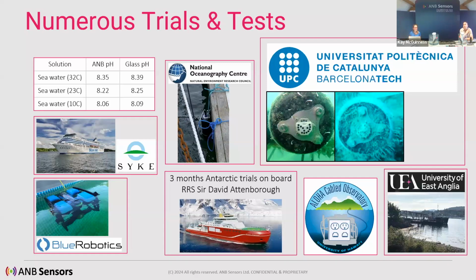We did some tests in Barcelona where we deployed two sensors. The one on the right-hand side has a lot of biofouling incrustations on its surface. That one wasn't switched on during the deployment; it was a control sensor. The one on the left had the monitoring switched on, and you can see there's no biofouling on its front surface. That's because we generate a small amount of peroxide during deployment, and that peroxide is enough to keep the transducer surface clean from biofouling. Obviously, peroxide breaks down quickly in water, and therefore isn't a long-term contaminant of the solution.